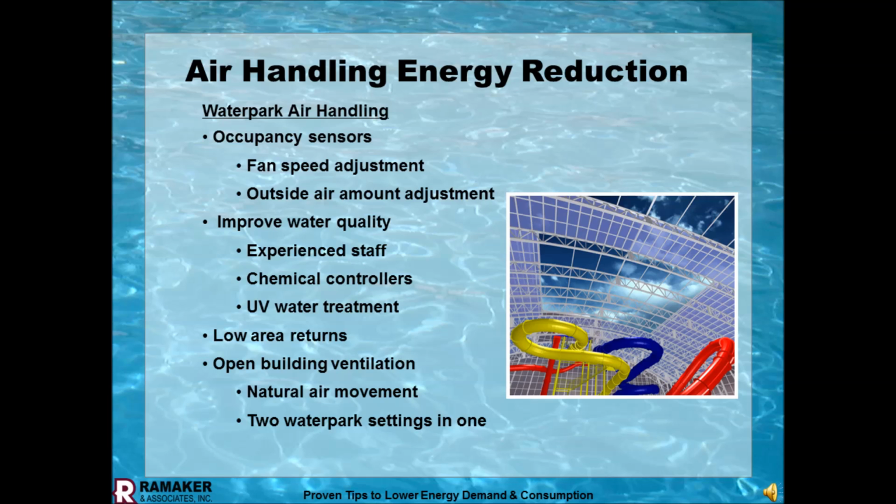One of the items that can be added to a water park, if not in the original construction, is the large ceiling fans. What's the benefit of the large ceiling fans? You've got a lot of heat sitting up at the ceiling. Move it down and around, circulate it around the building. Move the air around so you don't have condensation concerns. And the next thing is you're moving the air around so you don't have a chloramine buildup. Again, it's the bad water making bad air. The chloramines are heavy. They hang out in the low area, and that's where the swimmers are. The lowest point is the pool at chin height. So yes, and even with the best design, you get dead spots.